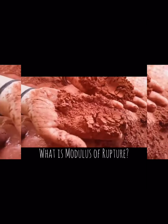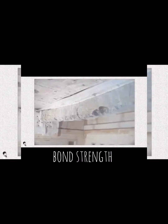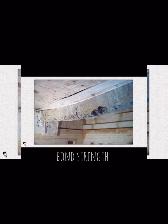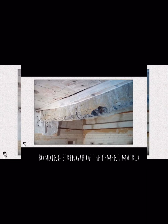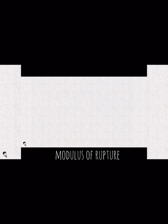But what is modulus of rupture? Flexural strength measures the bond strength of the test specimen. For castables, it measures the bonding strength of the cement matrix. In a flexure test, modulus of rupture in bending is the maximum fiber stress at failure.